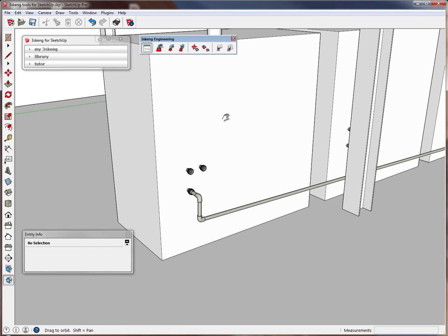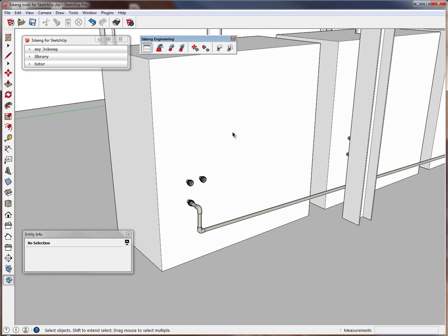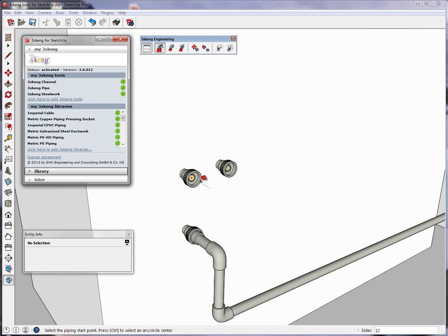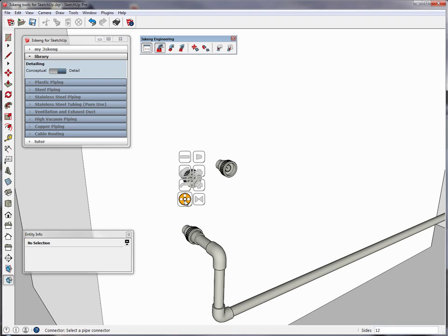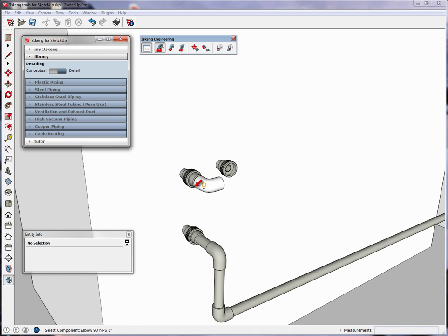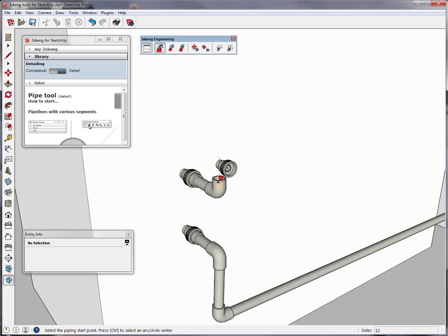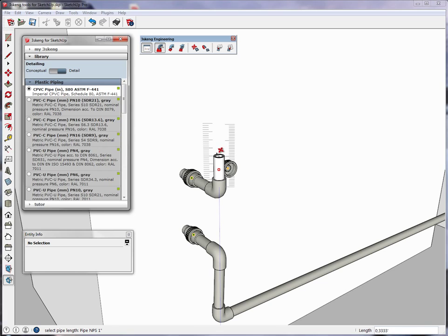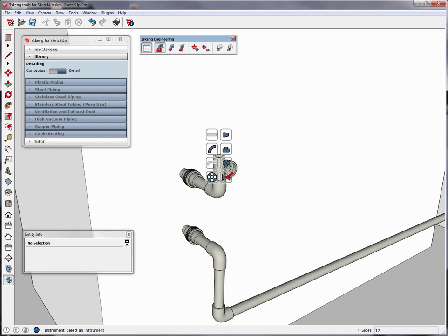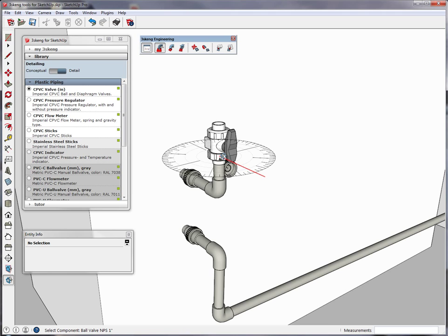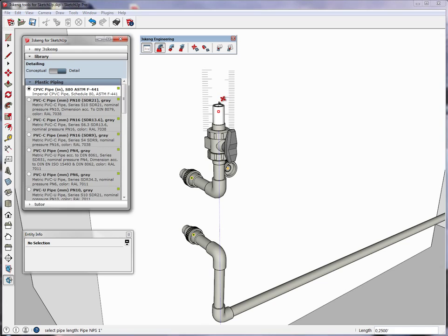Now we will proceed with the PCW supply and return. We add the male counter piece and use the pipe elbow to align the axis with the drains. Have another straight pipe. Now we want to add a ball valve. Align it. Add another straight piece.